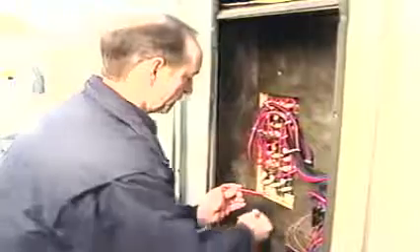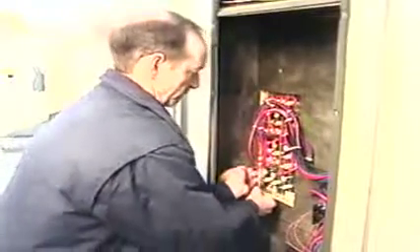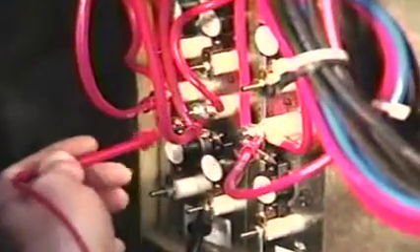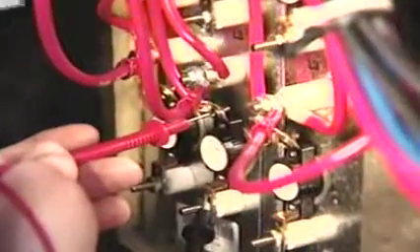In the real world, verifying the complaint, gathering information, and visual inspection overlap, and the order that you do them in will vary depending upon the situation. The important thing to remember is to check the simple things first before you get out your tools and start taking things apart. If the root cause of the problem is obvious, you can go right on to step 5 and correct the problem. But if the problem is not obvious, you'll need to dig deeper and perform whatever component or circuit tests are necessary to isolate the problem.